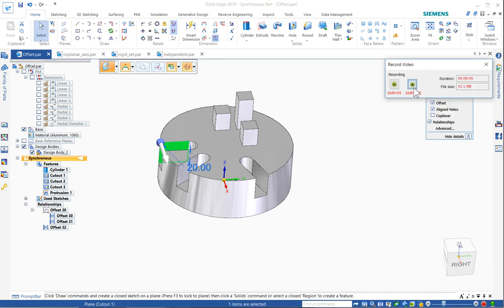So the behavior is this now. If you click this face, or if you click one of these, you use the edit definition handle. I'm going to do a symmetric edit. So notice these 3 buttons. Select similar offsets. So these are the ones that were done all at the same time, and you see those change together.